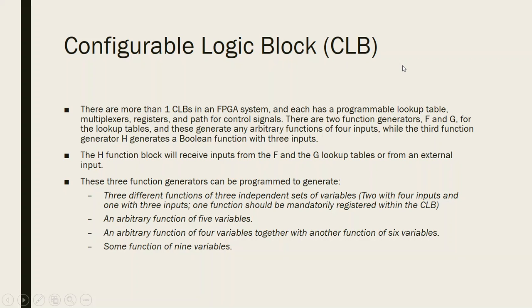Now when I say a function generator, it's not the generic function generator that you'd use in the laboratory to do your experiments on frequency response plotting of an inverting amplifier or something. These are function generators because they generate a Boolean function, right? So H block receives input from F and G lookup tables or from an external input, depending on how you have configured your FPGA chip.